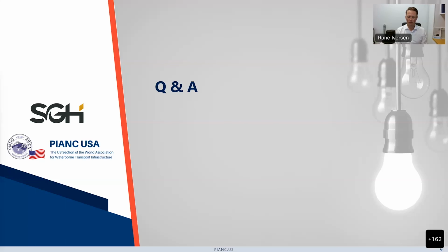The velocities that are published now are all tug assisted. But I think we will have some adjustments of the velocities based on non-tug assistance. Without the tug, you will have a vessel that's much more difficult to control, and you will expect to see higher berthing velocity.